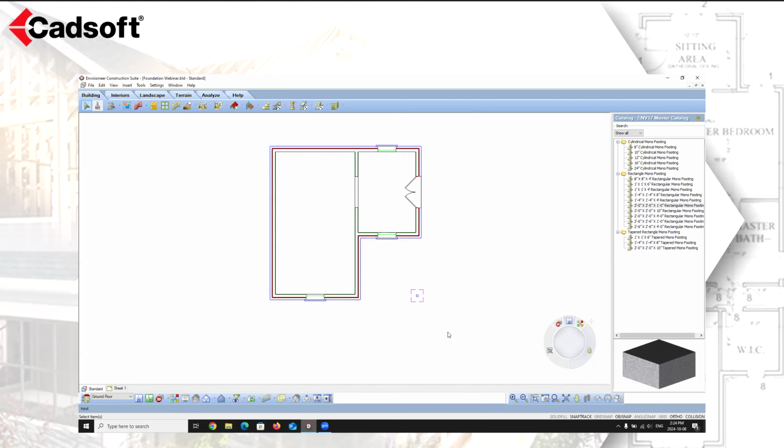So just to review, the Foundation Builder Wizard takes all of the work out of creating a foundation. Various construction styles are available, and once the foundation is created, you can customize the individual walls and add elements such as columns and pad footings. The Foundation Builder builds a foundation by tracing the perimeter walls of an existing location above it. The wizard can create different foundation types, be it wall footing, basement, slab on grade, or monolithic.